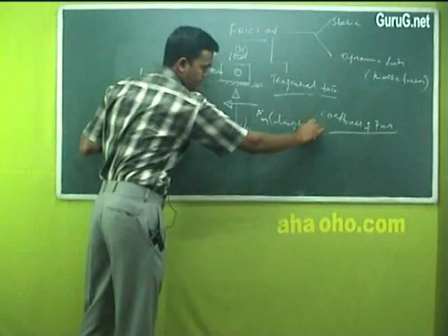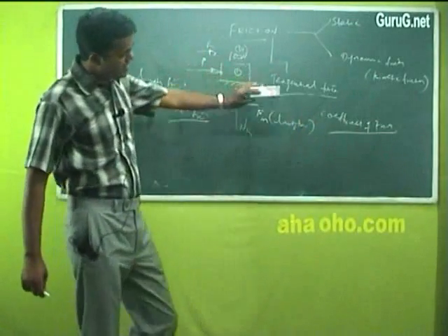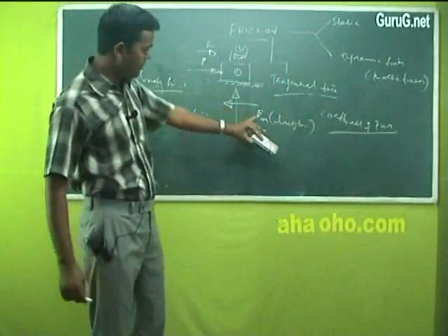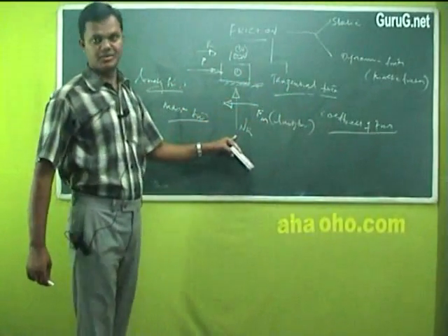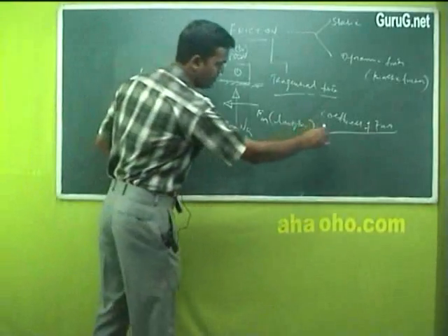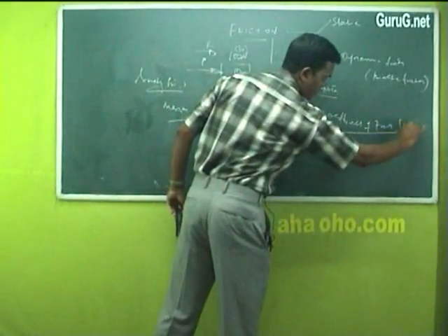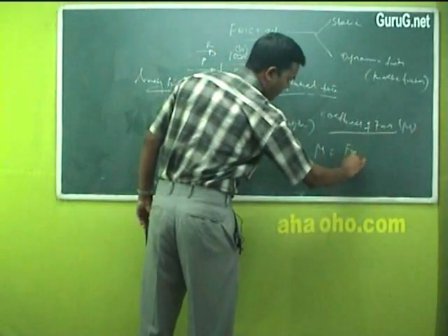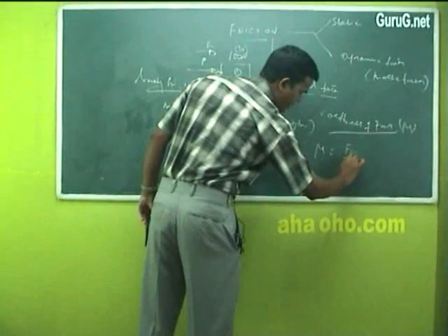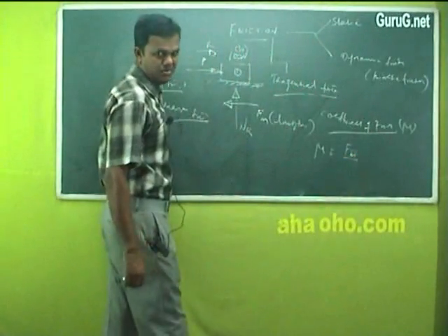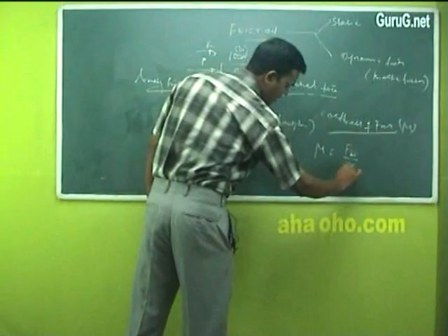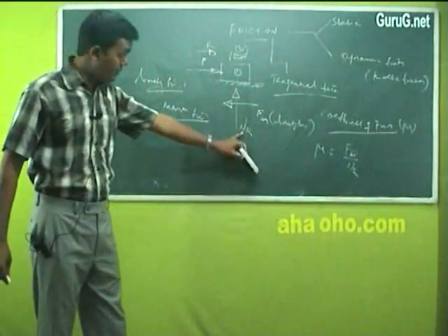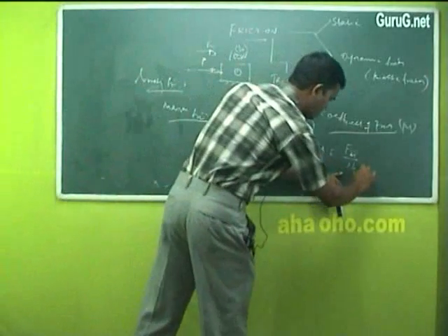Limiting friction. Right? So this coefficient of friction is a value which is the ratio of your limiting friction and the normal reaction. So I can write, the symbol is given by mu. Okay? So this mu will be Fm, that is F suffix m. It is not F into m. Please remember, it is F suffix m, limiting friction, divided by N suffix R. N suffix R is your normal reaction. I could always write this N suffix R as equal to W.